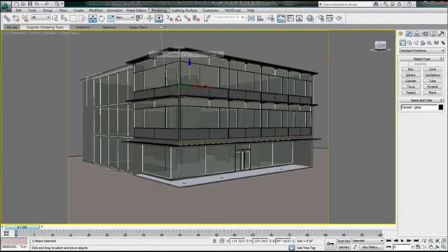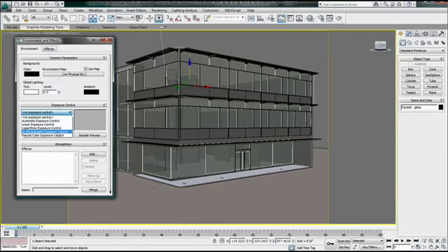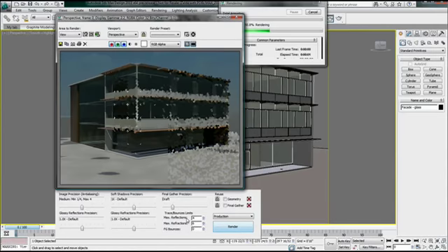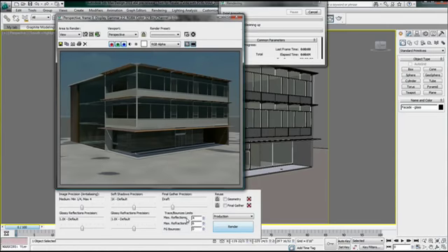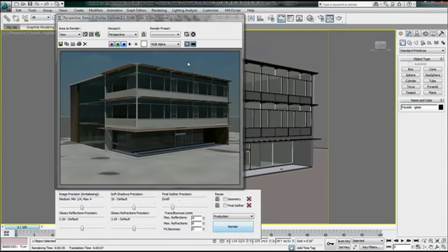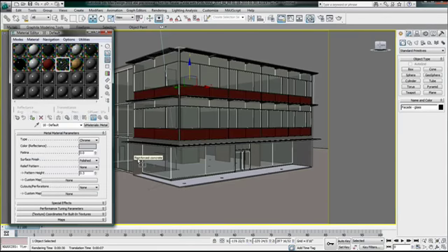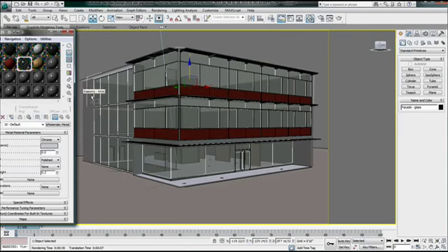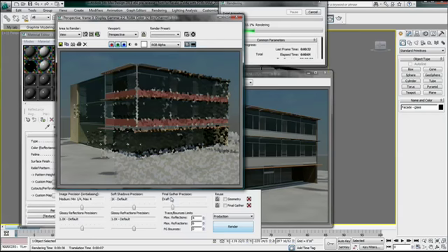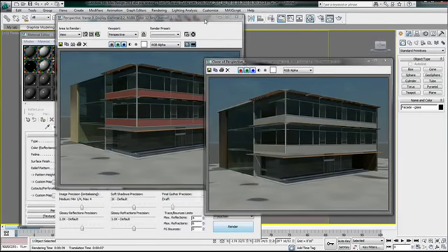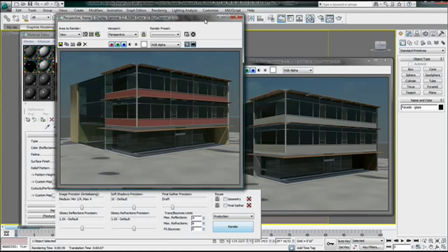The only thing I need to do from here is adjust my exposure control and either start rendering, create shadow or light analysis, and start my visualization process. You do that by applying different materials to the object and re-rendering to compare the results. Meanwhile, the Revit model is evolving and I will need to upload these changes while keeping the new materials I have applied to my model.